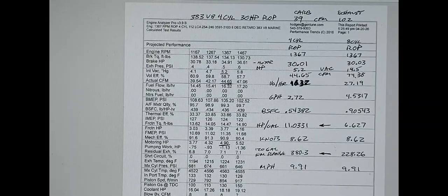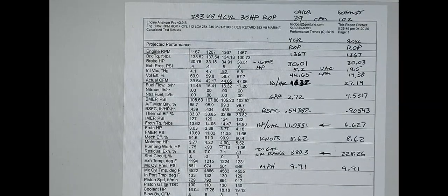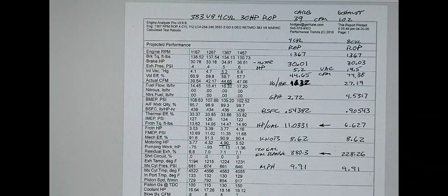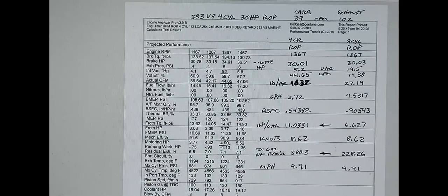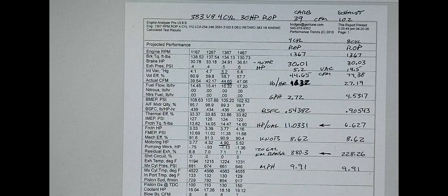Here is a rich of peak only comparison, and it's 8-cylinder engine versus 4-cylinder. Now, how do I run the 4 cylinders? What I do is I let one of the float bowls run empty. Once that float bowl is dry, it's running on 4 cylinders, and those 4 cylinders would be the outside on one side of the engine and the inside on the other side. Got even fire and order, and should run pretty smooth like that.